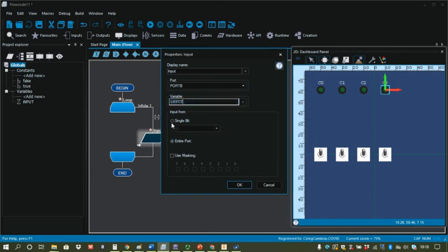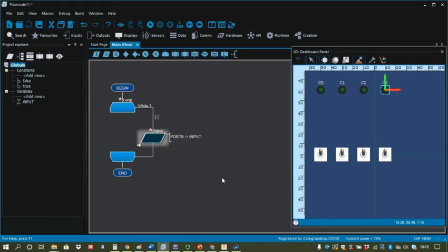Now this time as well I'm going to use the entire port, but I'm going to use masking, and I'm going to tick 1, 2, 3, 4. That means if anything is active on any of these 4 lines, then the system will just ignore it. It doesn't matter what their levels are. So just keying it to make it just the switch lines.